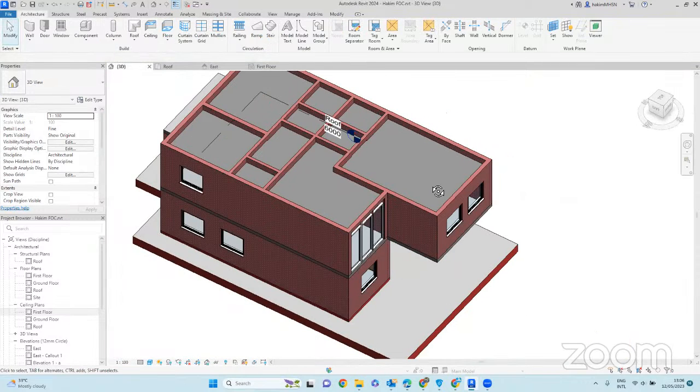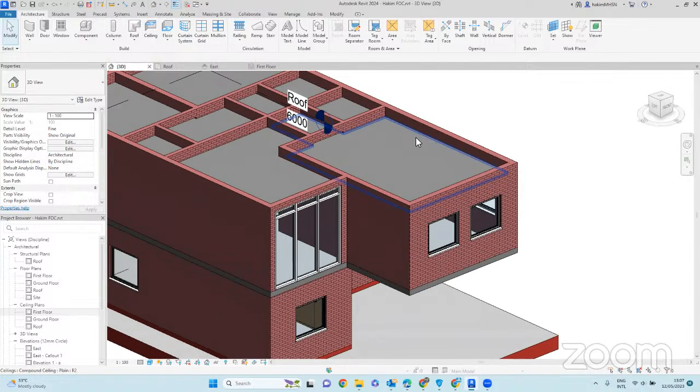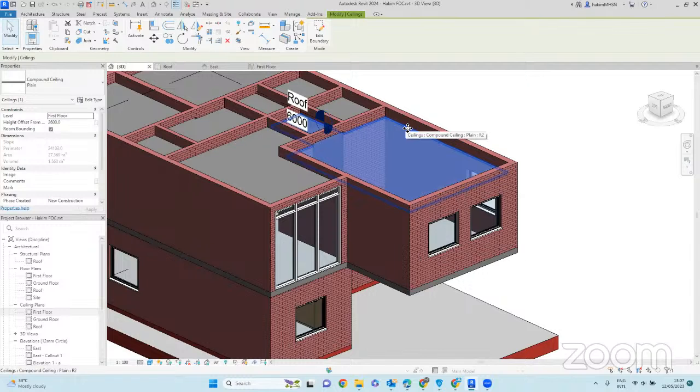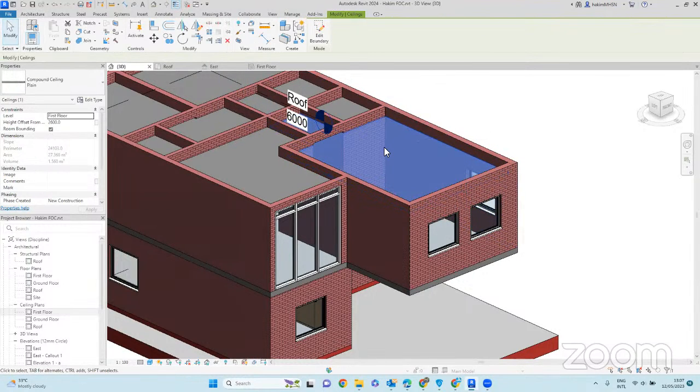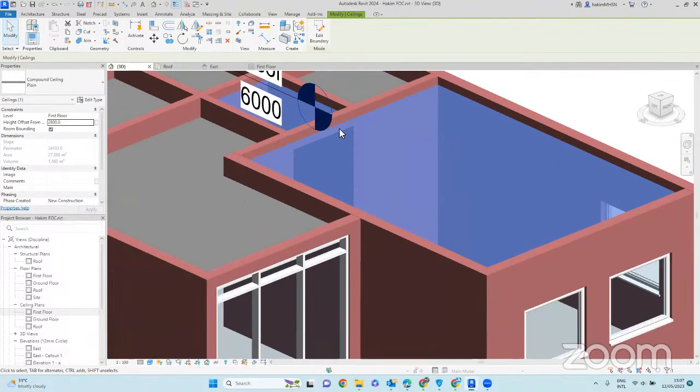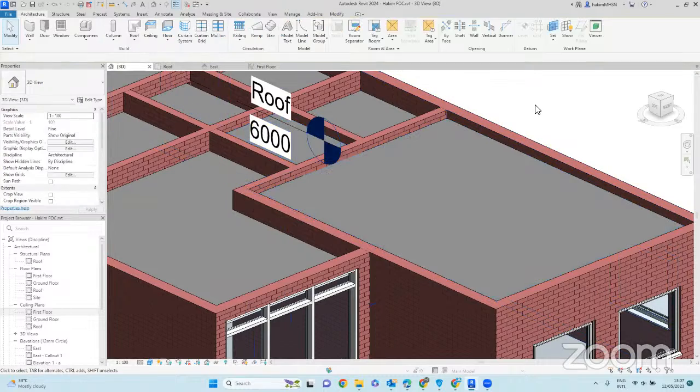And if you have placed the ceiling, but only then realize that you want to change the height, you can still do that by just clicking on that ceiling, and it will bring up the same properties, and then you can just change this value. So let's say I just want to make it a little bit higher, so 2800. Okay, now you can see it moved and it's higher than the rest. Okay, so that is ceiling.